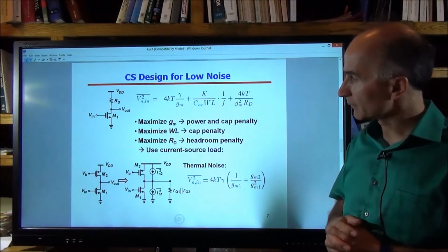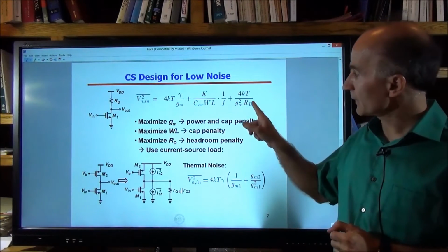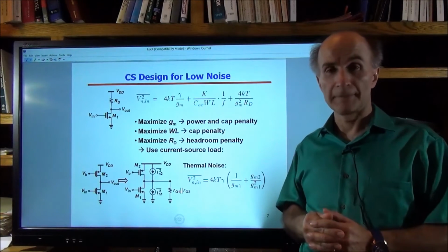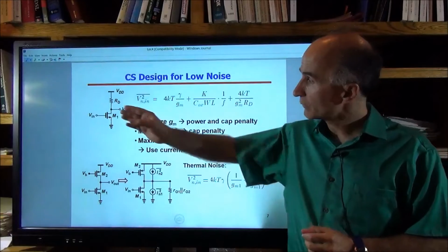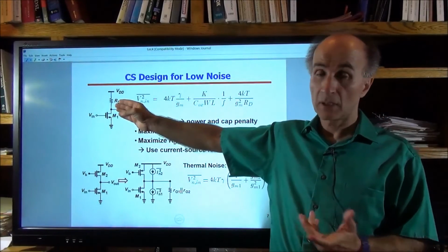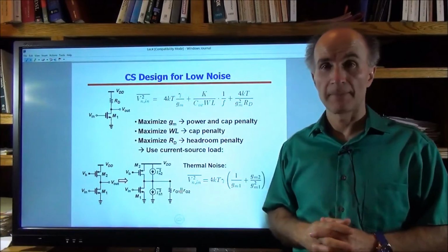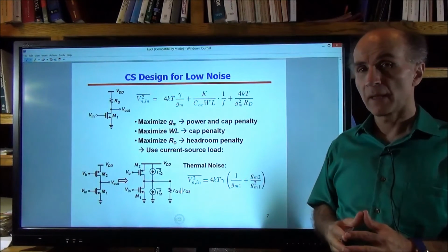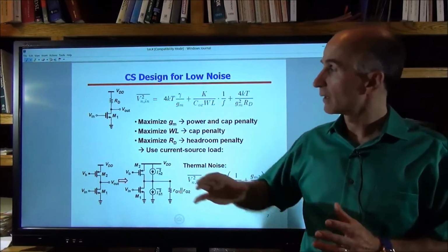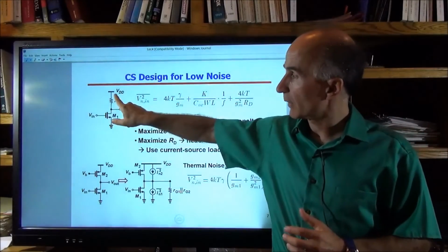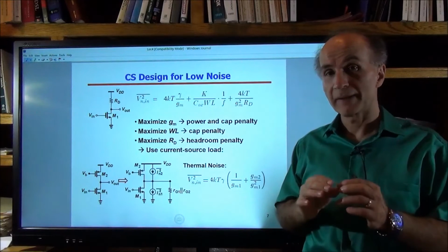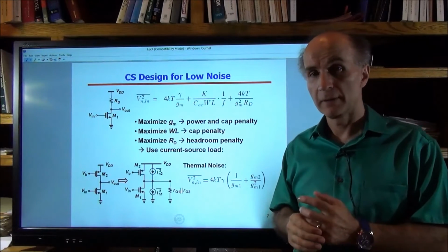All right. Now, if this term is bothersome, we can have a remedy. So this load resistor is here really just to provide the bias current for this device. Now, I'm looking for a load that does not have this limitation of this voltage drop, which is given by Rd times Id. In other words, I'm looking for a load that does not satisfy Ohm's law.